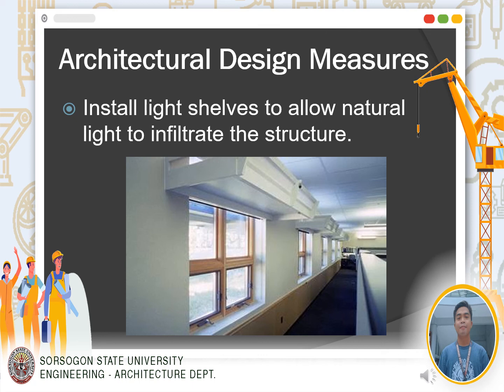Building orientation is also a factor, and consider the location of the daylighting sensor, because the window shades, soffits, and location of the light shelves and light fixtures interfere with sensor sensitivity to daylight. Human comfort is important, and proper lighting and thermal comfort are critical for satisfaction.